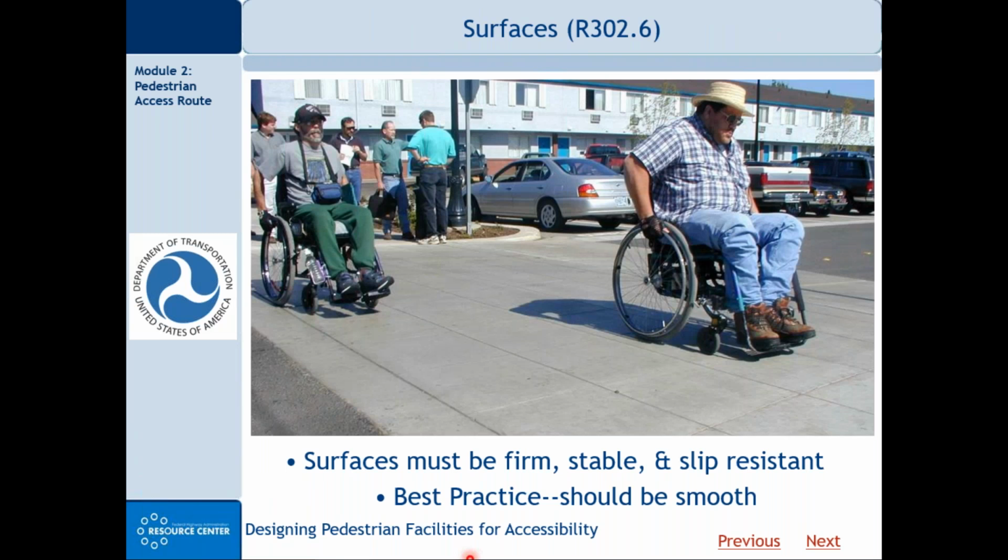That's a good question, and not to try to evade the question, but the answer really is it depends. This is an area where probably technical infeasibility will apply. You want to try to flatten the driveway where it crosses the sidewalk a little bit to reduce the cross slope at the sidewalk. But we also have to recognize that the driveway has to allow, as I said earlier, vehicles of certain types to enter and leave and use the driveway. So you have to sort of balance those two things.